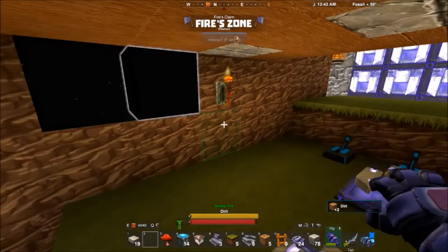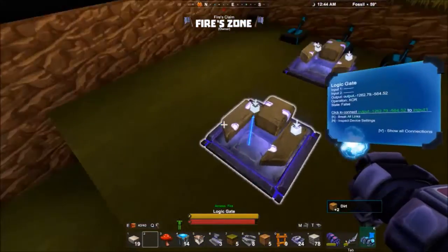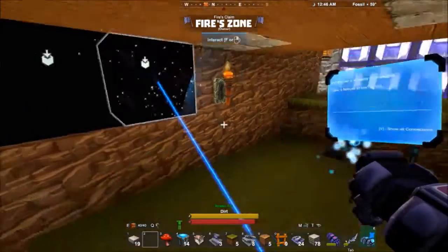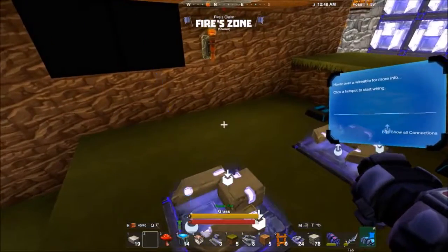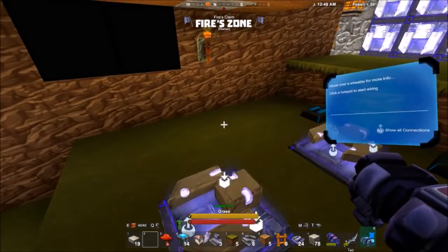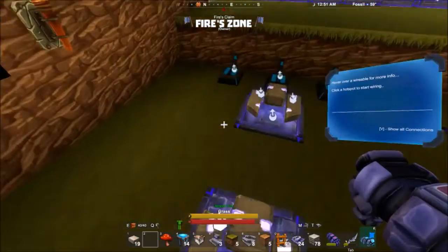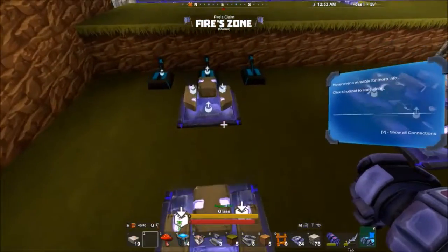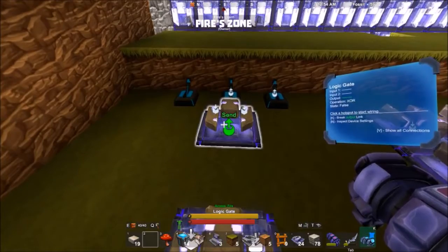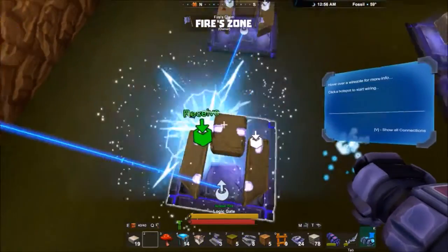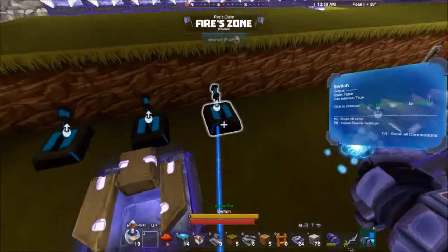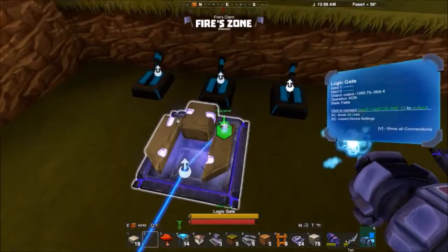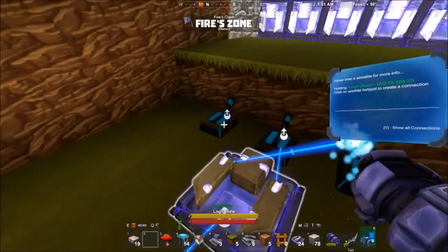Let's put it right there. The exclusive ORs are going to give me the actual sum for that input. Then later we're going to calculate the carry. So the output of this one is going to come to here, this one is going to get the carry, and these 2 are going to get the inputs.